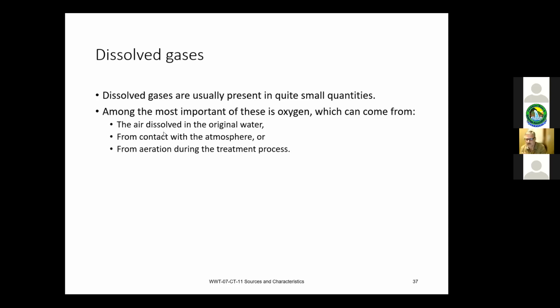Biological nutrient removal facilities start off with an anaerobic zone, which flows to an anoxic zone, and we'll cover this all more later as well. But then it flows to an aeration zone. If you're adding O2 by a cascading effect of water at the beginning, now that wastewater has additional O2, and it hits your anaerobic zone, which is supposed to have no air, and it will contravene what's trying to happen in that zone.